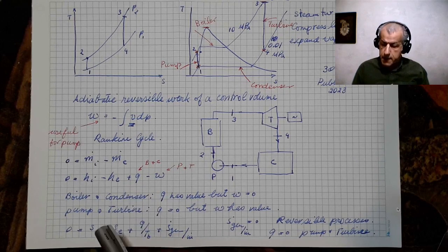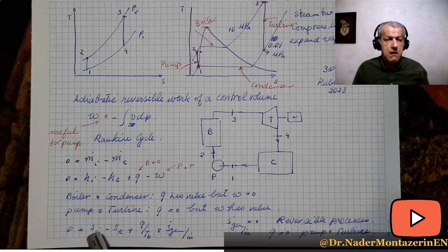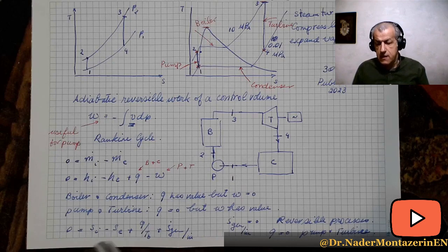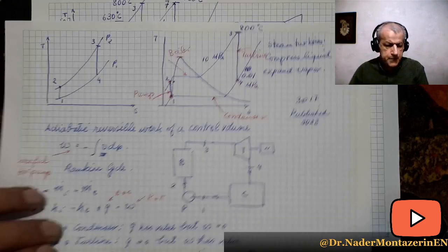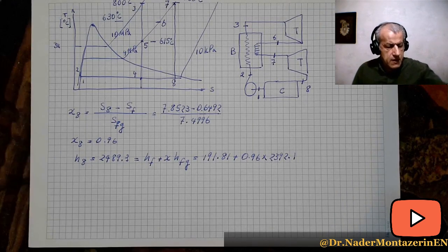So, if it is isentropic, then entropies remain the same between inlet and outlet. So the equations are very much similar to what we had, and this practice continues. The first step that we need to take is to calculate the efficiency of our turbine.